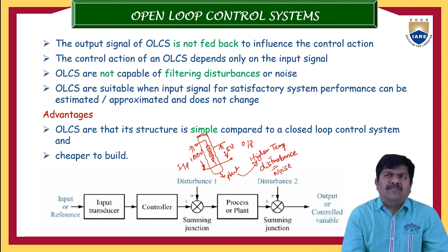Noise is not an exact word here, but more or less disturbance and noise are signals which we do not intentionally require. So signals that are not required are the disturbances. Now, how can we differentiate them in electronic and electrical systems? These noises and disturbances will have different frequency levels. If the operating frequency is 50 Hz, the noise and disturbance frequencies may be other than 50 Hz, and such signals are called noises or unwanted signals. Those are the disturbances. In this example, the temperature variation could be seen as a disturbance, because I am not expecting it and I don't want to see temperature variations here.